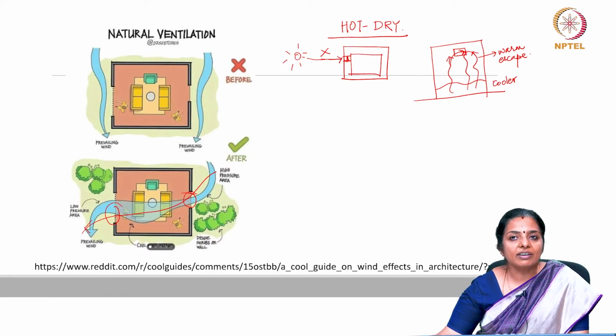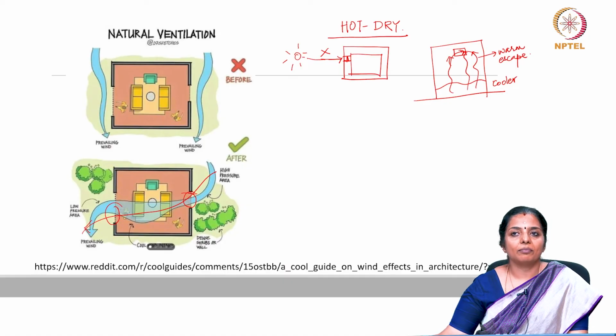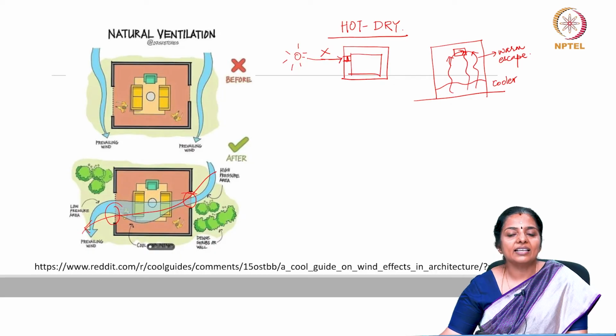If the natural wind is incident on any one of the windows, the other window and the door will act as outlets. Not being aligned, the airflow indoors will be better distributed. If the outside air is incident on both windows, then the large volume is likely by itself to make the conditions comfortable. The wind direction may not be incident on either of the openings, but on a window in another room.